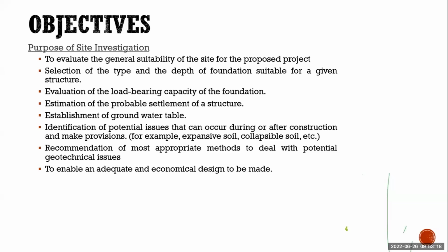Like, let us say if it is near a slope, we can know whether it is a landslide-prone area, or whether we will get any landslide in future. Or is there any drainage passing through that area? Are we going to block the drainage? Definitely you are not going to block the drainage, because it will affect your foundation or your structure later. So should we do any diversions? How can we do the diversions? Is it economical or not? In that way you can decide. So that is also the purpose of site investigation.